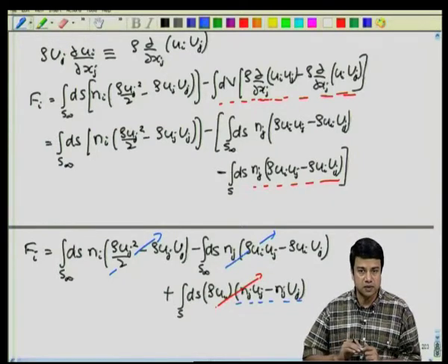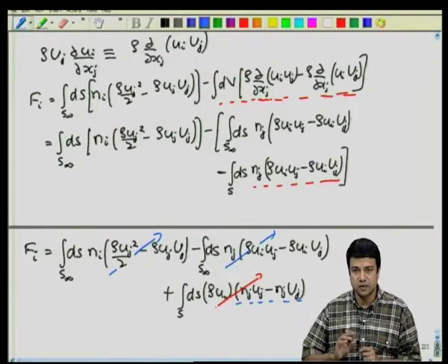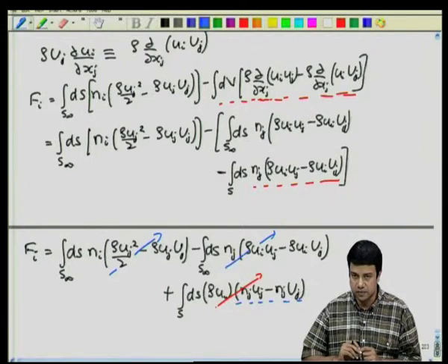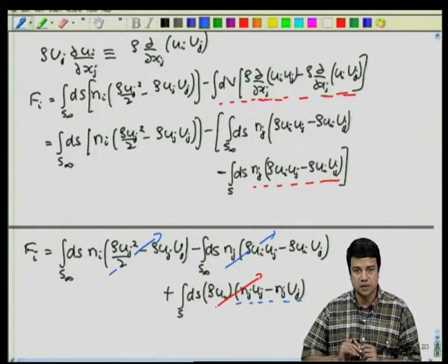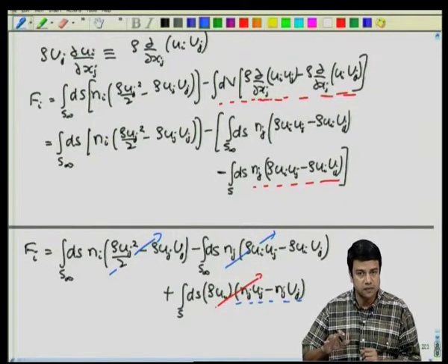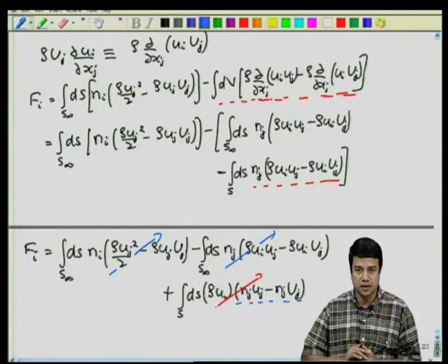Therefore, this has shown that for any shaped object, the net force exerted by the fluid on the object, provided it is moving at constant velocity, has to be equal to 0. When we did it for the specific case of a sphere in the last lecture, we used symmetry arguments to derive this, but this calculation shows that it is true for any object. I took you through this for a 3-dimensional object because I will be doing a similar calculation for a 2-dimensional object when we look at 2-dimensional potential flows in the next section.